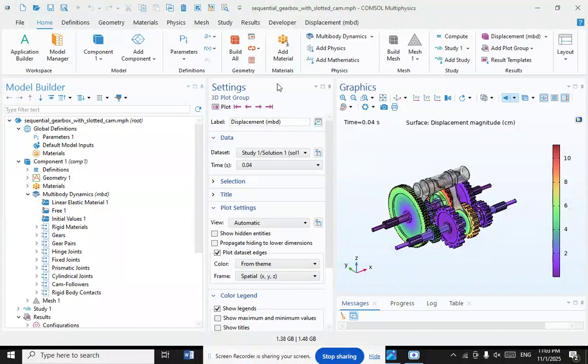Reverse gear. Even in a modern transmission where all of the forward gears are in constant mesh configuration, often the reverse gear uses the older sliding mesh or crash box configuration. This means that moving the gear shaft lever into reverse results in gears moving to mesh together. Another unique aspect of the reverse gear is that it consists of two gears, an idler gear on the countershaft and another gear on the output shaft, and both of these are directly fixed to the shaft. For example, they are always rotating at the same speed as the shaft.